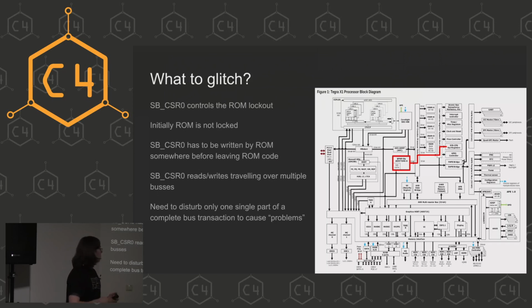And we only need to disturb one single part of this bus transaction to cause problems. And we don't even care how we are going to disturb it. It just needs to break somehow. It can write a wrong value to that register. It can write to the wrong address. The write could be too late for the clock cycle, so it is happening, but it's happening too late. All this kind of stuff.